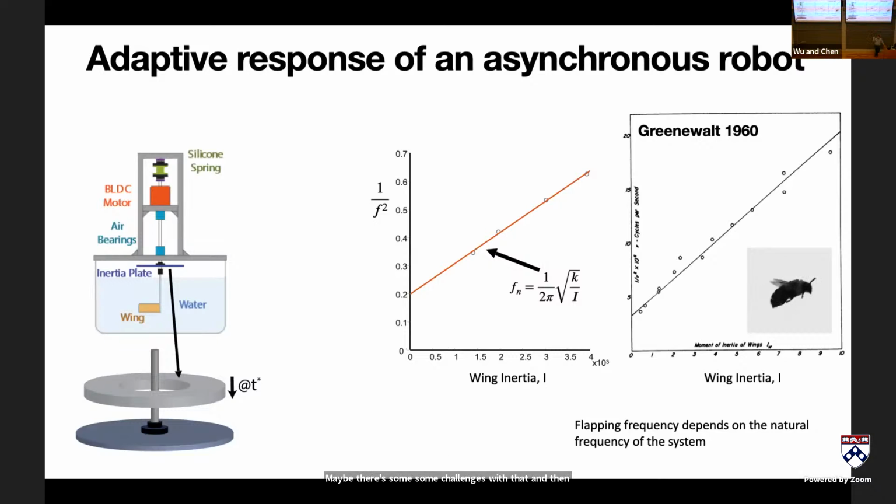And then with the rate controls that you have in delayed stretch activation, you can modulate the wing beat frequency, or you can choose it to track a different system natural frequency, which is the combination of the body dynamics as well as the actuation dynamics. I don't know, that's kind of a poor argument for why this. I think it's more in service for understanding the biological system. But I think the general idea of using autonomous generation of wing beats is really interesting, and I think it provides a lot of cool opportunities.